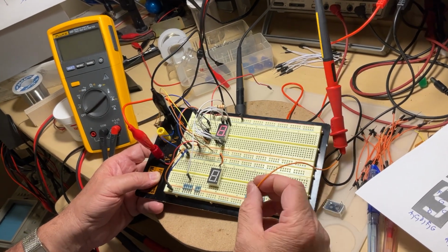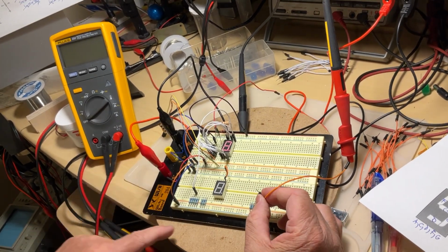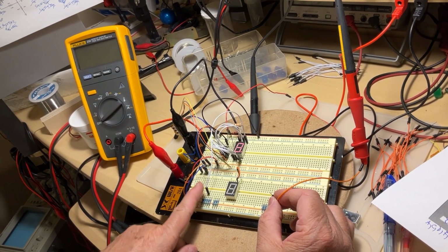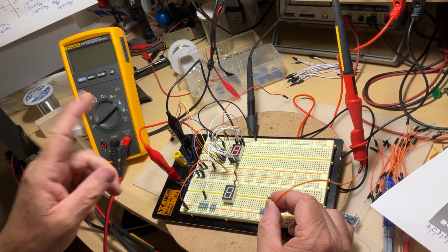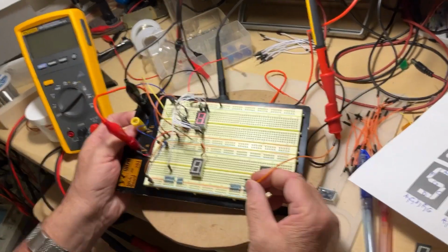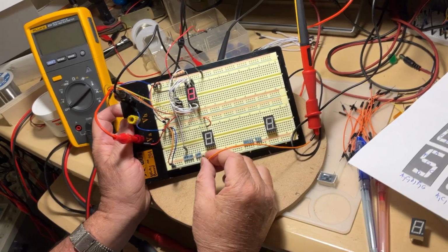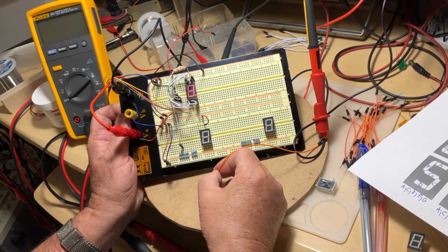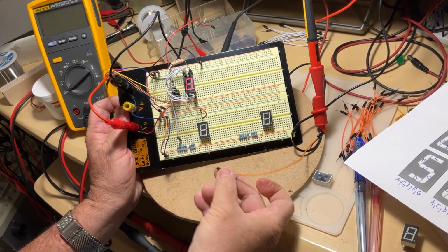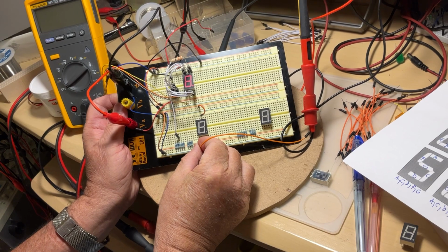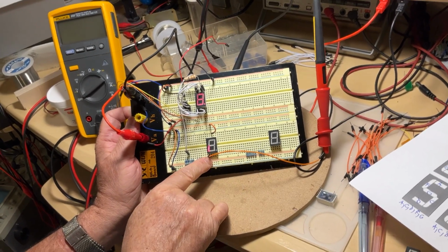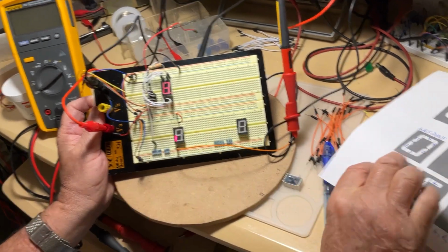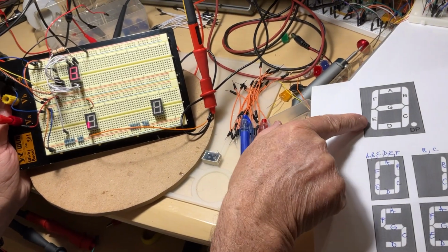And then I'm going to apply from the ground here through the resistor. One resistor I need. I'm going to apply energy to each pin one by one, and then I'm going to see what pin is assigned to what segment. So let's take a look. Pin number 1. Oh, when I touch the pin number 1, this LED goes up. What is this segment? If you take a look, it is the segment E.